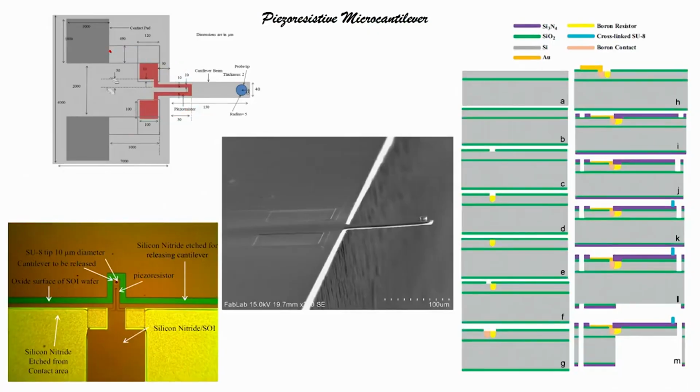Coming back to the screen, like I said, this is your resistor, and because the material that we have used to diffuse into this silicon is boron, it will be a p type piezoresistor. Because the polysilicon is n type, but that we do not really worry about. The point is that there is a resistor diffused into this silicon, now the cantilever.